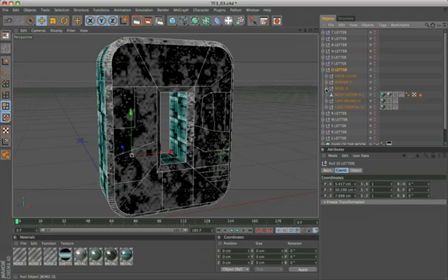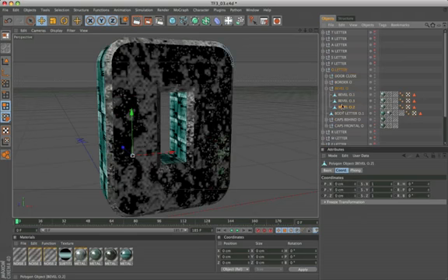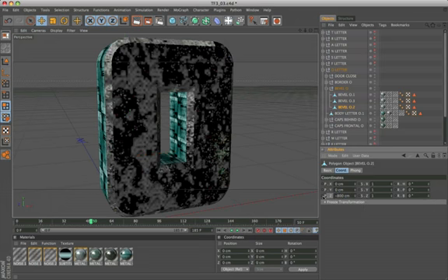We start the animation of the bevel. We select the bevel 2, go to frame 50, activate on Z -800. Go to frame 142, and insert 0.